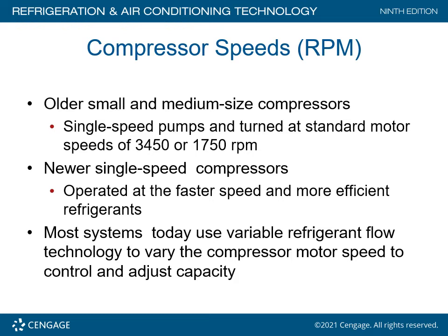We no longer have a fixed one speed that takes care of the air conditioning. Basically, now we ramp up, ramp down based on the actual load conditions measured at the thermostat. And by doing that, we can figure out if we need more air or less air based on information such as the dry bulb, the wet bulb, and the latent heat that is measured in the space.